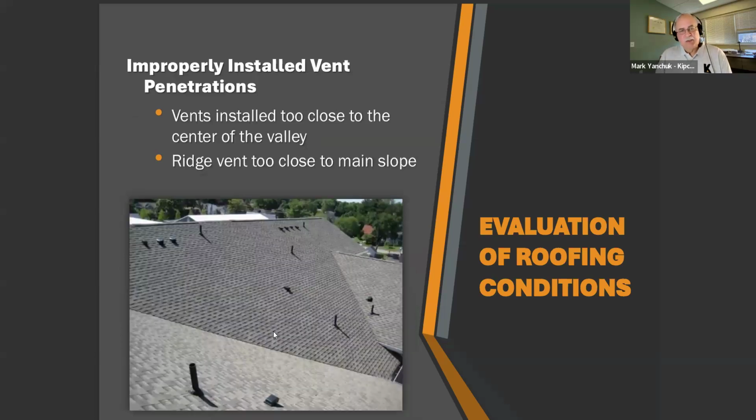Now, the issues with this roof might not be as evident, but they could cause roof leaks. So you have two roof facets here. You have the primary roof and you have a gable over here, which is a secondary roof. So runoff flowing down the main roof hits this valley. And if it's a torrential thunderstorm or something where the water's coming with velocity, it's actually going to turn up and go up this roof slightly.